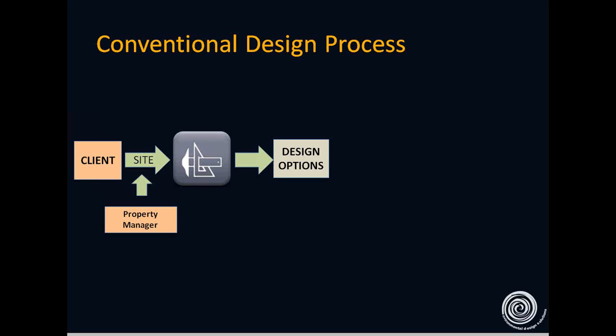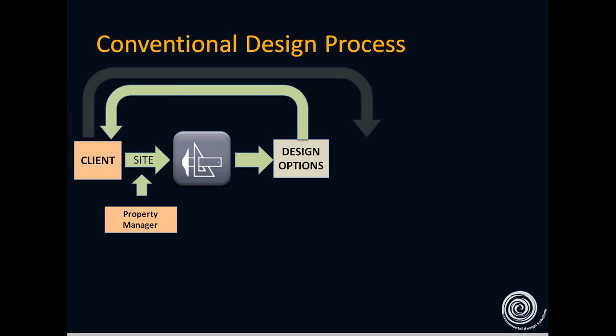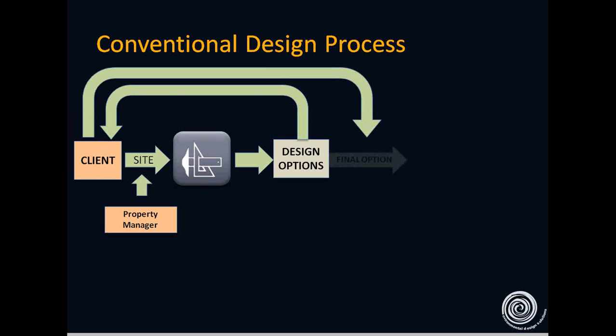The architect and the client agree on the design concept consisting of general massing, schema, orientation, fenestration, and general exterior appearance, in addition to the basic material. The consultants are now asked to implement the design and to suggest appropriate inputs in the design. Each consultant works independently and develops the DBR, detailed design. The architect then incorporates the requirement for each consultant in the present design.